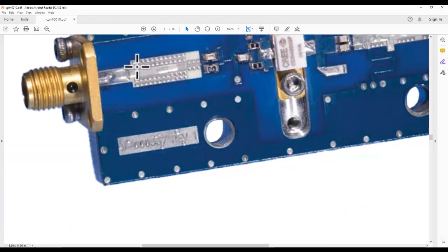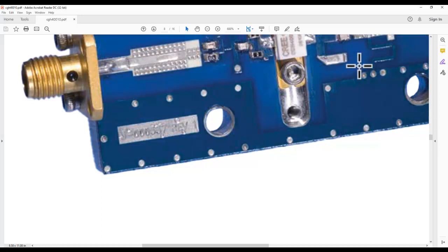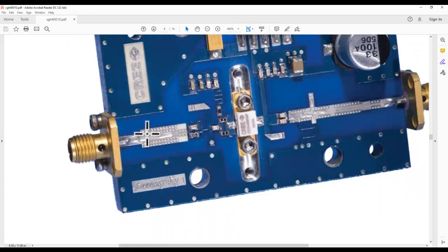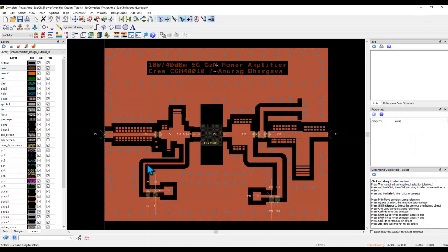So in that case, what I'm going to do is the concept which we typically use, and that you can even see in the demo layout design which vendor has provided. Notice what they are doing. Small rectangles along the RF signal path wherever you need, and if you're using any open circuit stub, even the ends of that stub could have those kind of stubs. So these things will help you do post-production tuning, because you can place a copper ribbon or a copper wire across these and try to alter the impedance of the line in order to tune the performance or the shift you have.